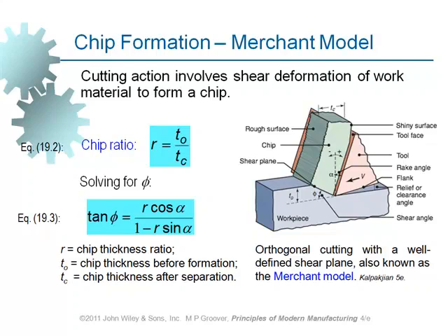And we could have an alpha which is representing a horizontal surface. For this case, the magnitude of alpha is 0. Or it could be positive, moving the top surface down just like that. This is negative rake angle, this is positive rake angle if this is the cutting tool. Horizontal is 0, then this is actually producing a sharper cutting edge, of course, when it is positive, right?